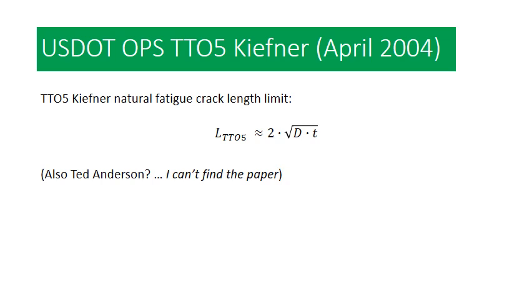I believe that there's also a crack length limit that's proposed by Ted Anderson. Unfortunately, I can't find the paper at this point, but I recall reading one paper that Ted Anderson had put together where he had done some finite element analyses of some failure pressure calculations, and he found that there was really a relatively short length of the crack where all the stress intensity was focused, and within his study there was sort of a natural crack length limit to be considered. Unfortunately, I can't find the paper. Once I find it, I might have to update this video presentation. We'll keep moving anyway.